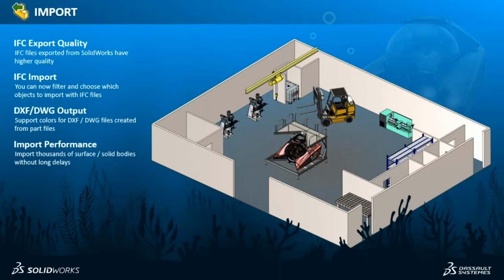So that's pretty nice because, well, frankly, we communicate with colors. So I have many companies that don't even call out hole sizes. The holes on their drawing are attached to a color, and people read a color chart, right? Green holes are 1/4-20, orange holes are 3/8-15, whatever. So we communicate through colors, so colors are important.